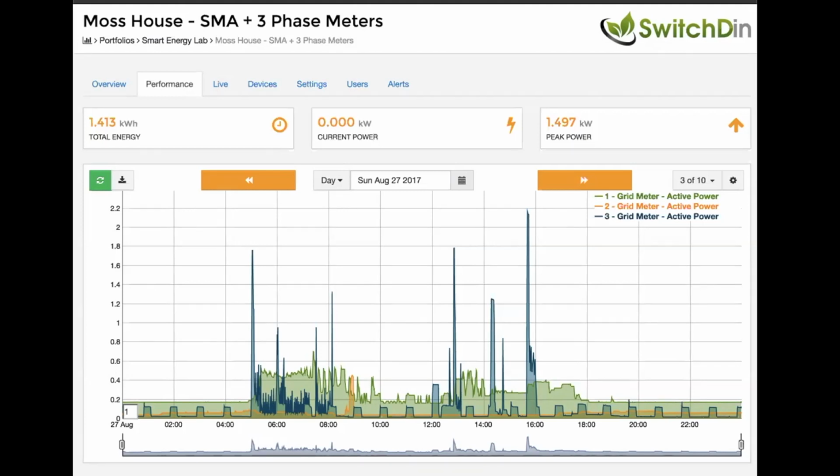It's interesting, you can really tell a lot by looking at a load profile. You can see some appliances and see their cycling. So I can tell what the duty cycle of my fridge is. It looks like about 30%, so 30% of the time the fridge is on. But the reason I'm showing you this is that if you have the ability to measure in real time, and this is, I think, 15-second resolution data, I can see coincidental loads. And if I do it over a longer period of time, I can scan back through and see what the coincidental loads are. So the highest individual peak here on this three-phase system is 2.2 kilowatts, which is probably my